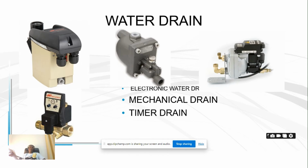This is a water drain. After your compressor, your hot air is cooled, what happens? Some condensation will come, and it is only the electronic water drain that will remove this condensate and purge it through this place, this place, this place. It will purge it out.